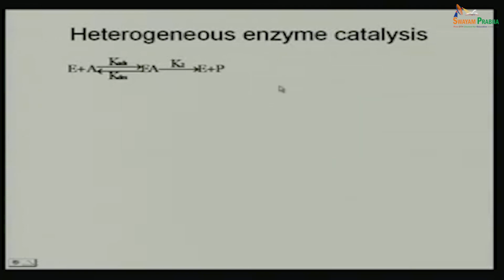What have I done over here? I have discounted the 2 diffusions: the diffusion into the pores, the diffusion out of the pores. So I'm just assuming that it's not even a porous solid. It's a simple case where there's just a solid with reaction occurring on the surface. But just a basic of heterogeneous catalysis. We'll go into diffusion in the next few lectures.